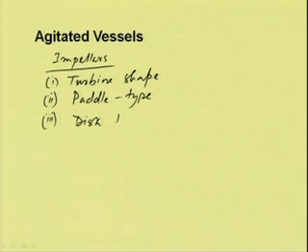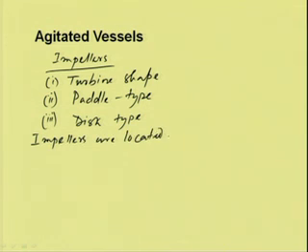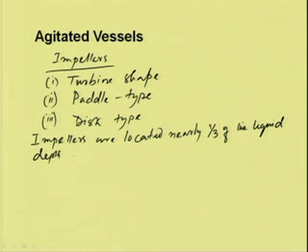These are the major applied impellers, and the impellers are located nearly 1/3 of the liquid depth from the bottom of the vessel.